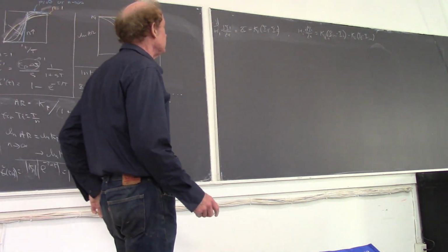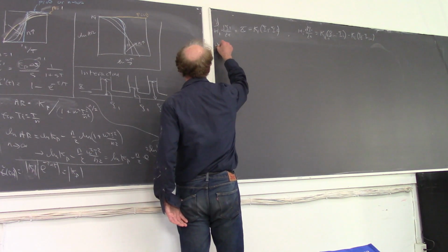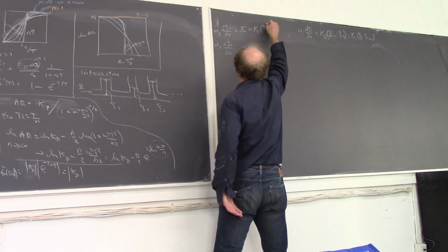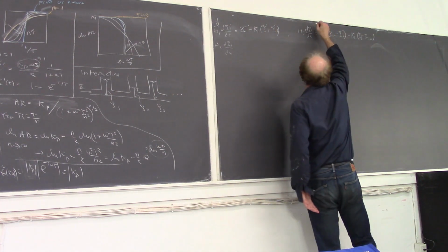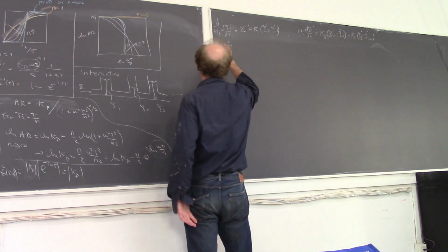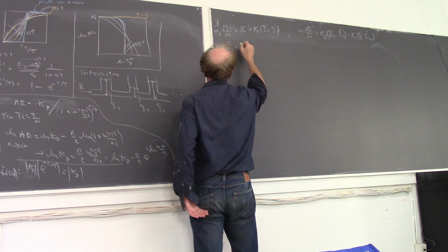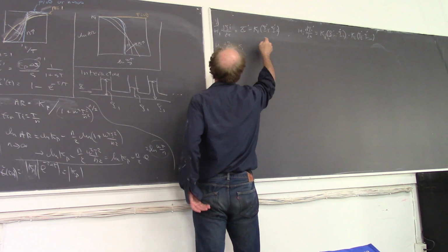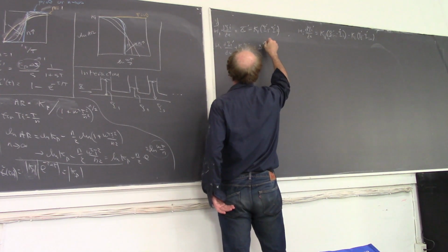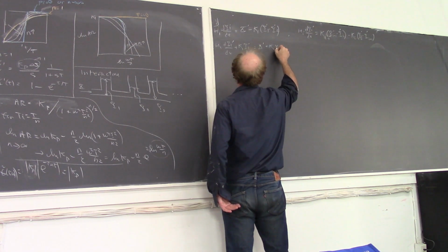Okay, so let's do the algebra. So if I rewrite this, I have h1 dy1/dt, and these are all going to be prime variables. h1 dy1/dt plus, so I want to bring all the y1s to the other side of the equation, plus k1 y1 is equal to x prime plus k1 y2 prime.